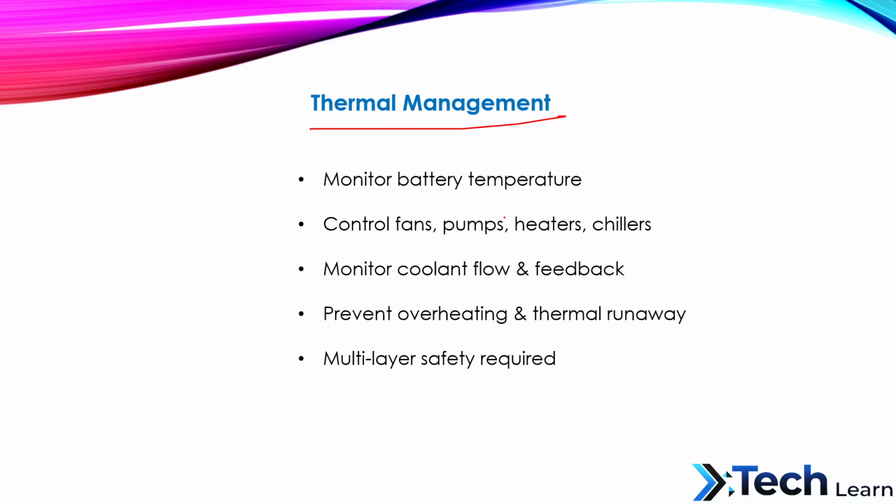For that, the BMS controls fans, pumps, valves, heaters, or chillers. Feedback from these devices ensures they operate correctly. Thermal runaway prevention is a key responsibility.